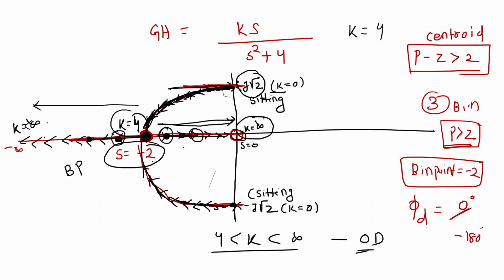Now, whenever I am coming from this j root 2, you are also coming from j root 2. We are colliding at which point? k equal to 4, right? So now at that position, we are at the same position. When we are at the same position, this is marginally stable, or it is called critically damped, right, sir? Not marginally stable. This is called critically damped. Okay, sorry. So at k equal to 4, this is critically damped.